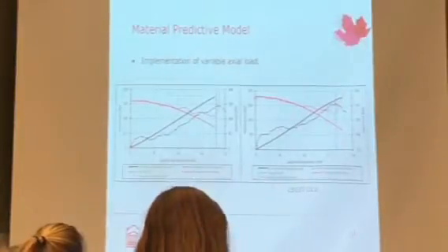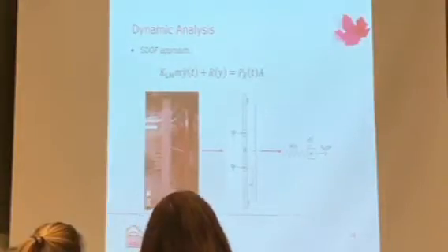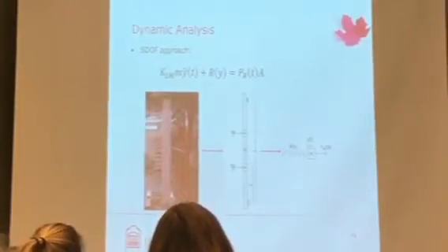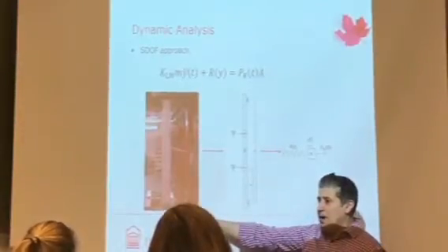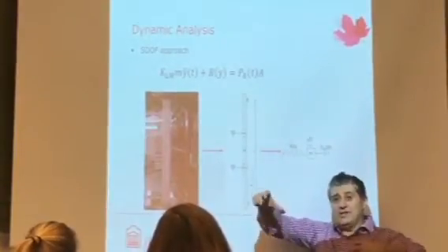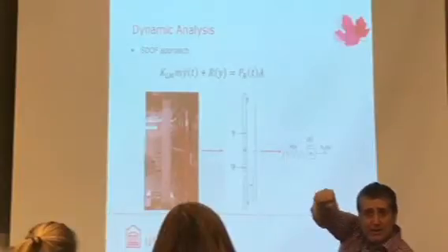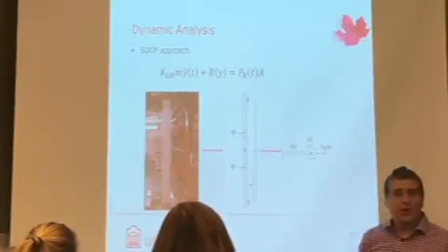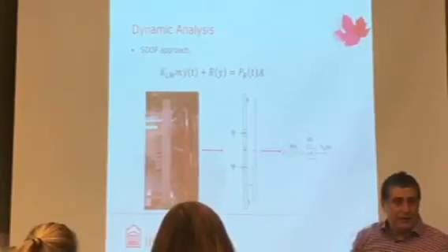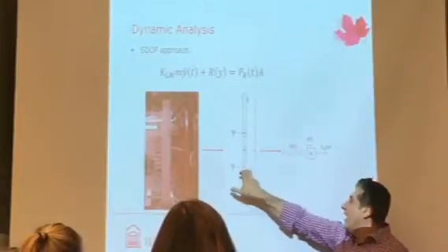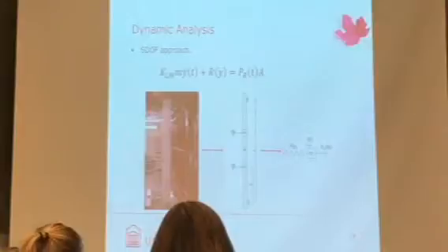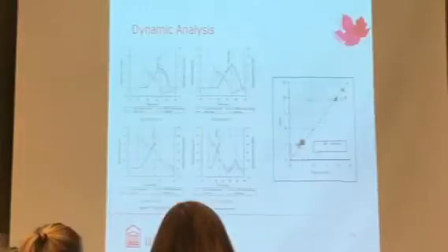The analysis is a little bit different in this case because you take a column, you have a load transfer device, so basically a steel member. You blow the air on the steel member, it has hinges, and as it moves out, it punches the beam or the column at 2 points. So it's a 4-point bending, right? So 2-point loading. And so what you have is you need a uniform mass, and on top of that, 2 concentrated masses, and you convert everything into a single degree of freedom. So it's a little bit more math, a little bit more involved, but essentially the concept is exactly the same. And again, we get fairly decent analysis results from that.